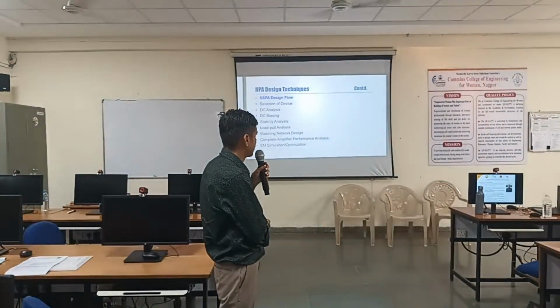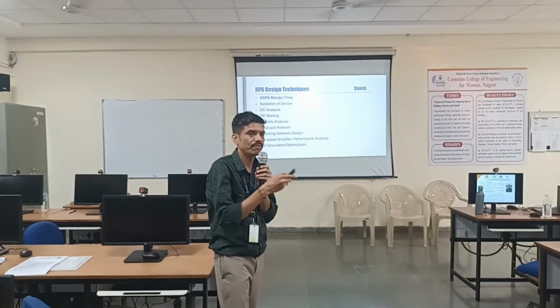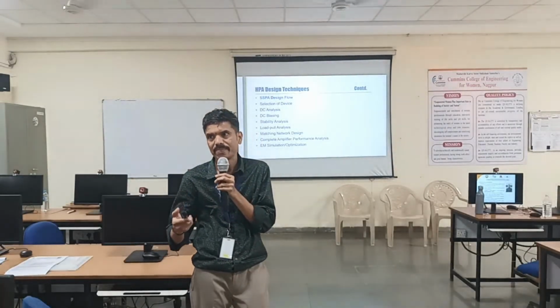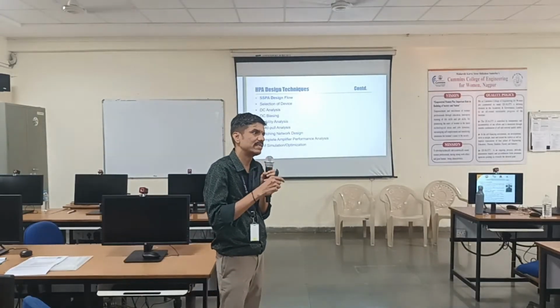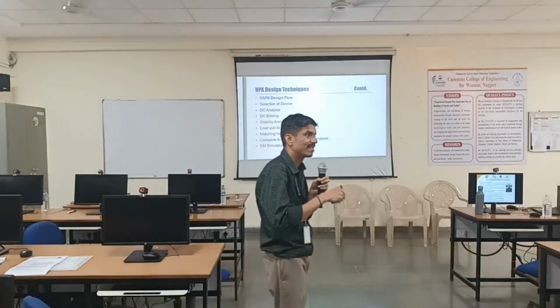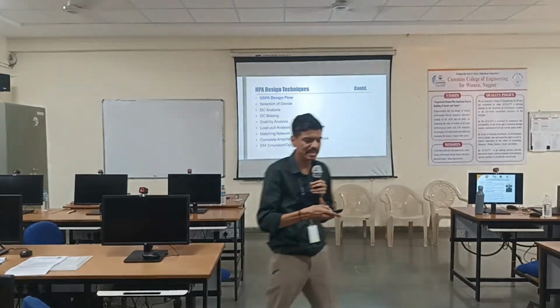We have to go for stability analysis. Stability is what I have skipped. What is the value of K? What is the value of delta? That we have to decide. Based on that only we'll understand whether this transistor will be stable or unstable for a given frequency. So that is called stability analysis.